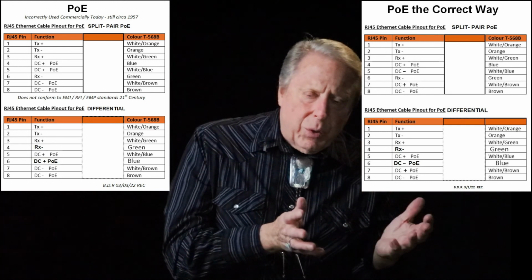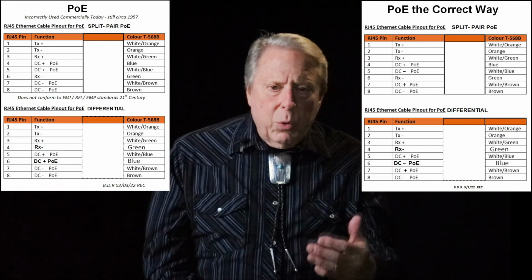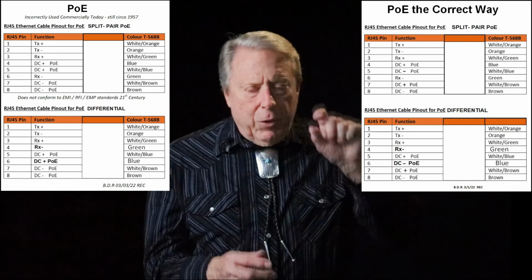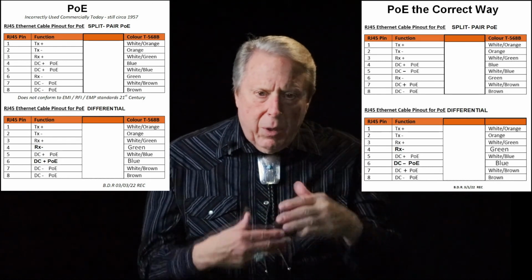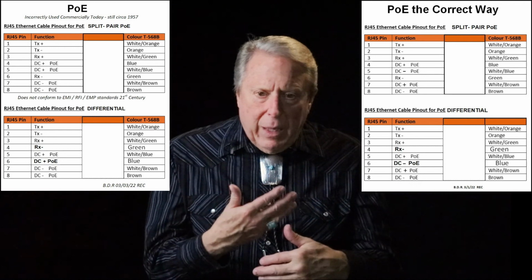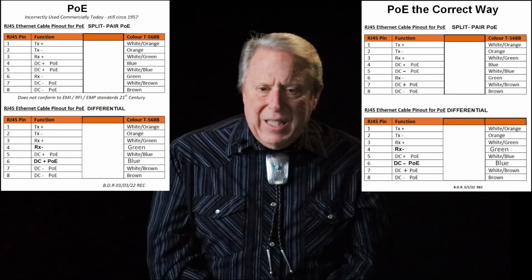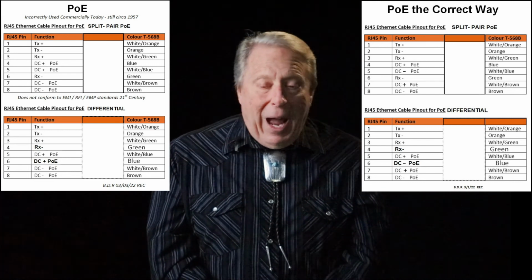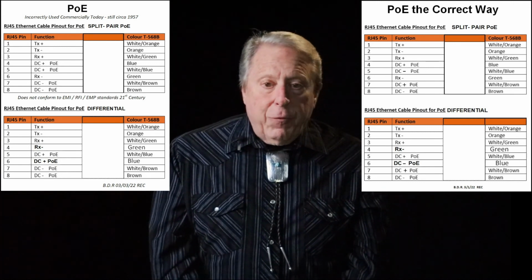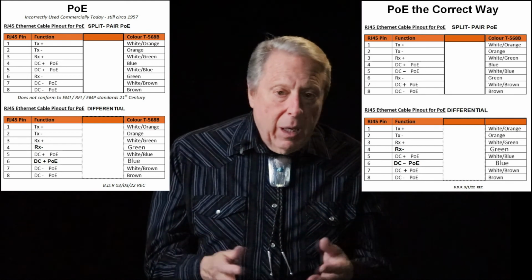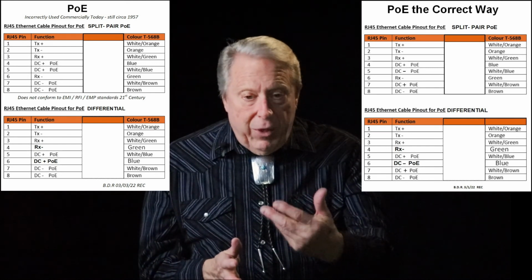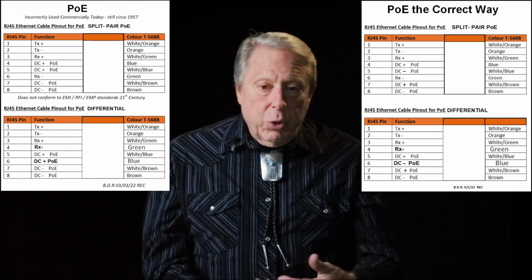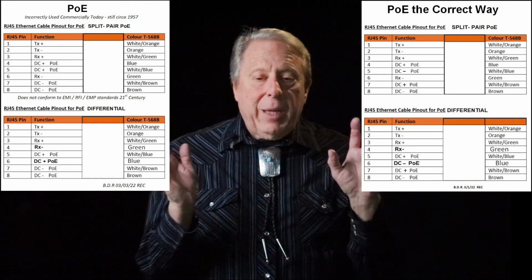On your differential side, you want to use that minus, the minus VDC and minus DC, rather than having two pluses together, two minuses together. You want that negative in between, because that is DC negative voltage, the return voltage, actually is a shield. And if you're worried about transient energy getting in on your cable, laying it out in this pattern allows you to use that ground to shield against anything coming from the outside.